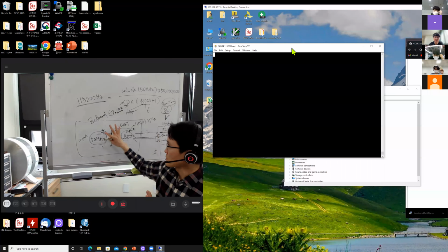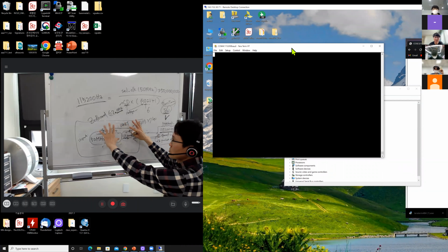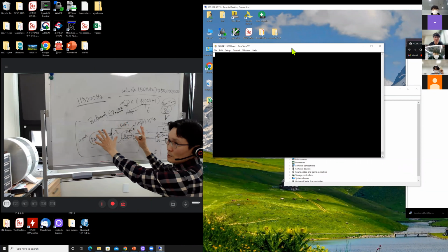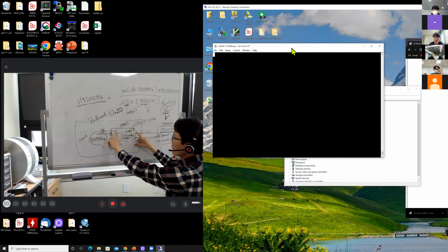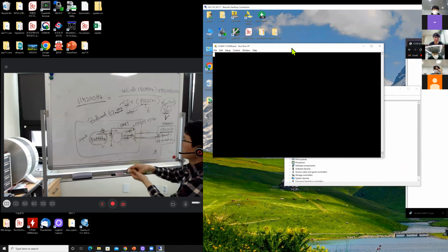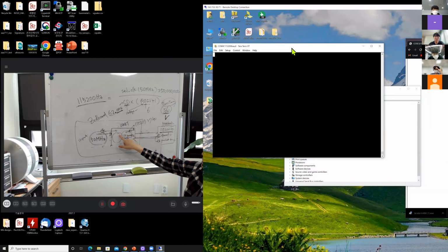So on the JetBot side, we have to prepare software, right? You have to make the UART ready for communication, meaning you have to set the configuration, the same speed and packet format. And then you can send the data.